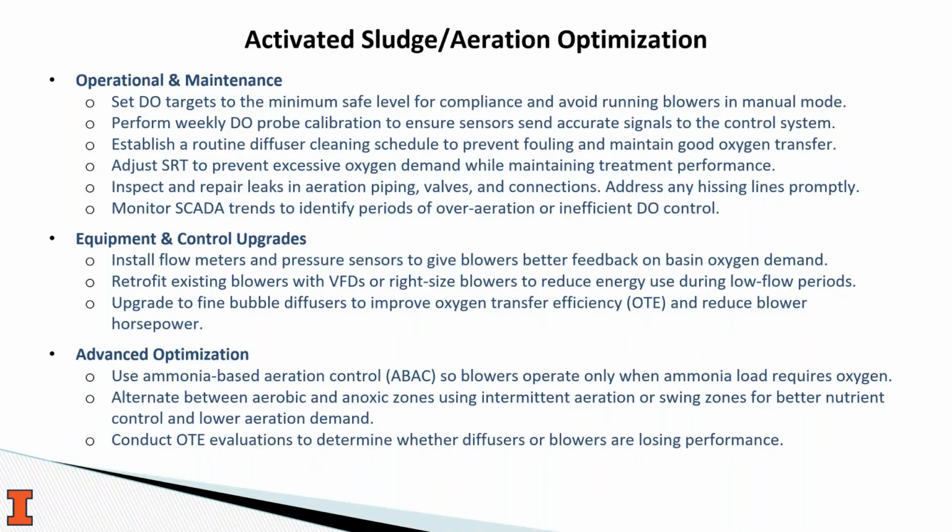And upgrade to fine bubble diffusers, which I'm assuming a lot more facilities have converted to from coarse bubble by now. But if you haven't, fine bubble diffusers can significantly improve OTE, oxygen transfer efficiency, allowing blowers to run at lower energy.